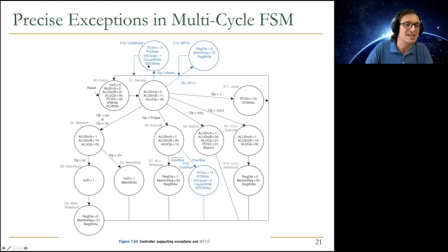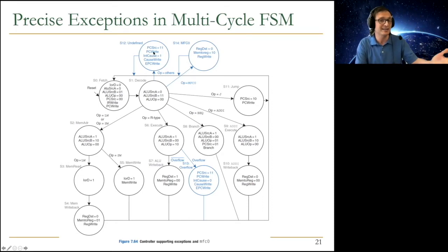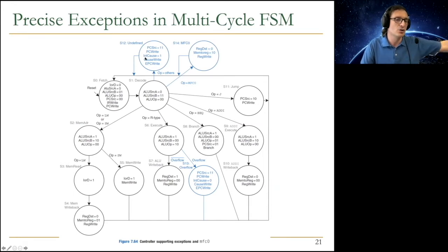And you basically change the program counter based on the cause of the exception to a particular exception handler, which in this case will handle the undefined opcode. And you may actually go to some place to fetch the instructions. And this may actually be a place where you emulate the instruction in software, right? Which I'm not going to get into. But you can see that we easily add another state to handle the undefined opcode exception when you decode an instruction. Some bits that you fetched are garbage because they don't correspond to any opcode that's implemented. If that's the case, it's an undefined opcode, and you need to handle that exception, right, in the decode stage.